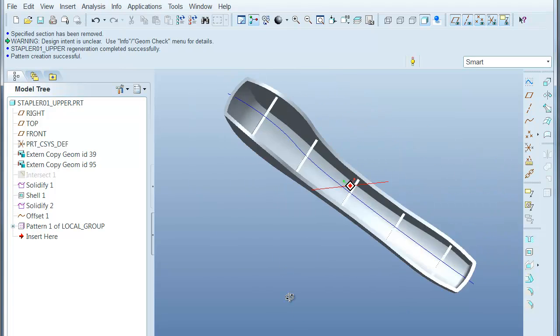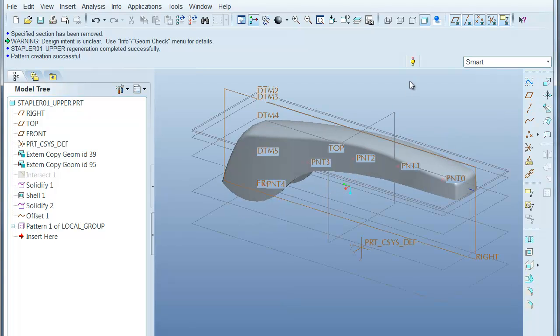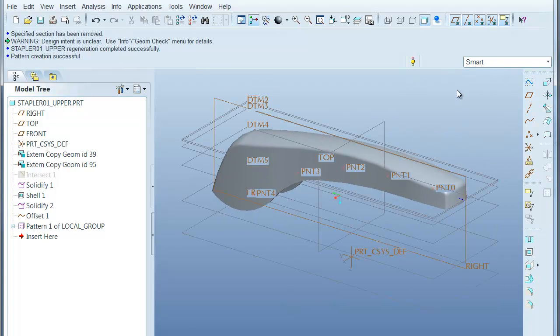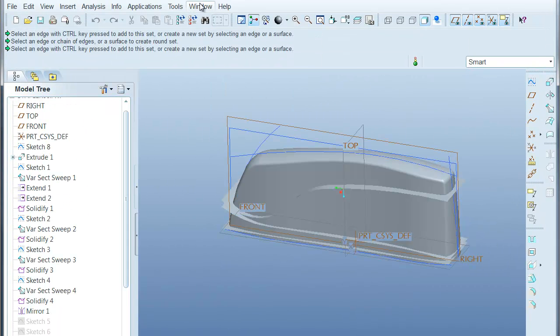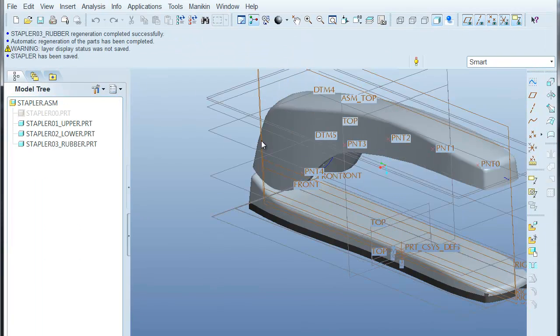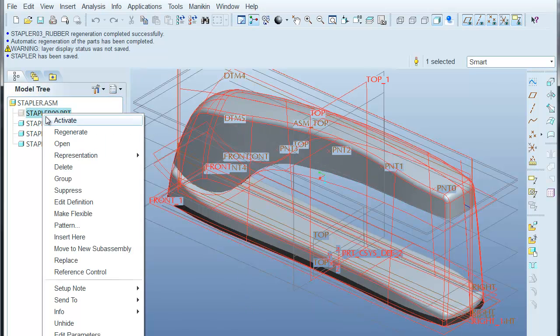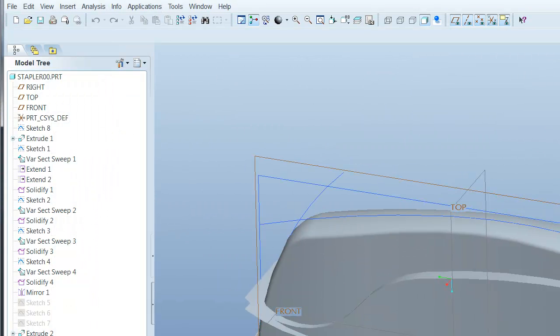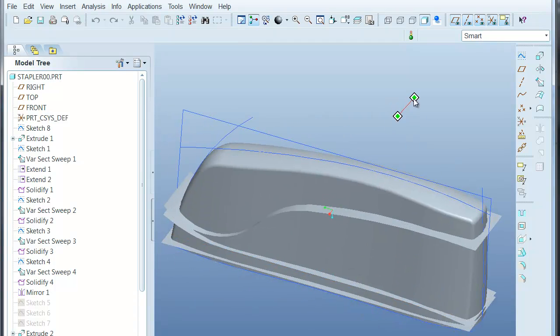Alright, so one last thing I might want to try to do is manage how wide the part grows. When companies like Nike have to, the engineers have to present their concept and their engineering ideas to a group of people, and there's always one person in your office that's trying to trip you up and make you look dumb in a big meeting. So what I'm going to do is try to set this model up so that I can just grow the entire geometry, and it's not going to fail. That one guy, I'm anticipating, is going to say, can't you make it any wider?